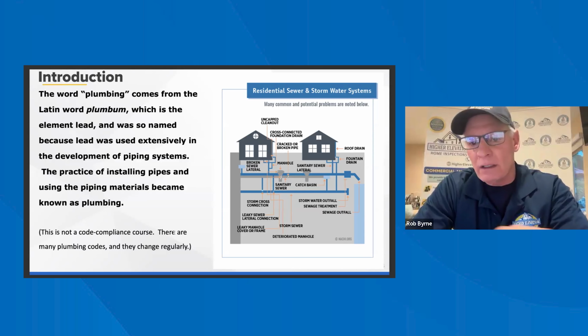Now, our stopper is holding. So we will take a picture of the water in there. I'm checking. I don't find any leaks. Now underneath here, typically we want to see water shutoff valves for the hot and the cold. Older houses, it was not a requirement. If we have PEX with a manifold, it's not required. But on most houses, you will see individual shutoffs.